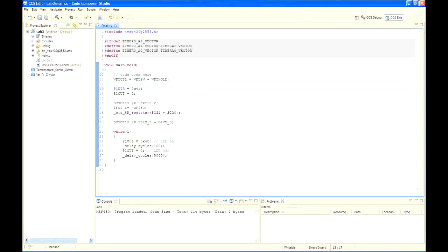We also want the red LED to start out on. So change P1OUT = 0 to P1OUT = 0x01. In step 17, we need to select the external crystal as the low frequency clock input.